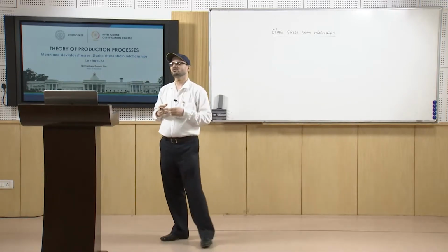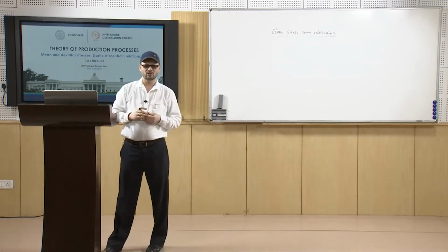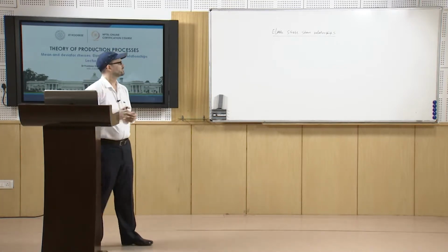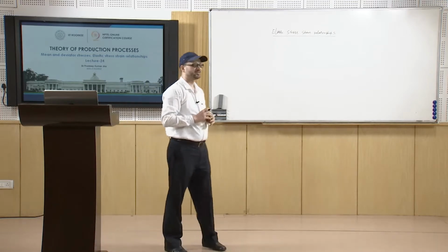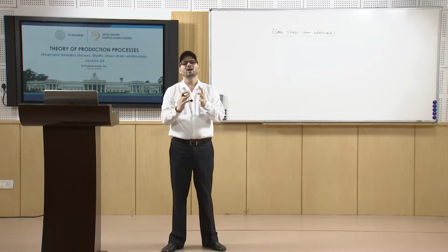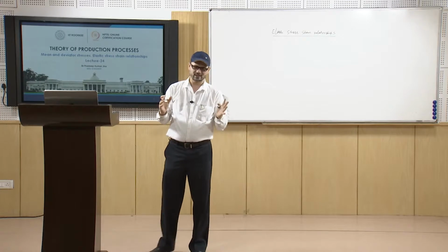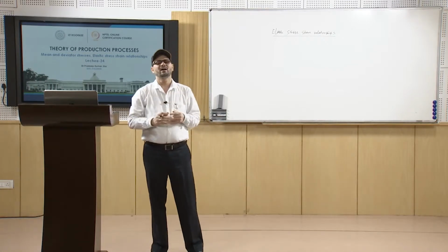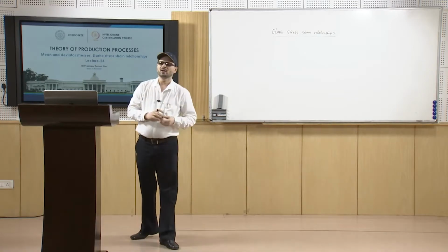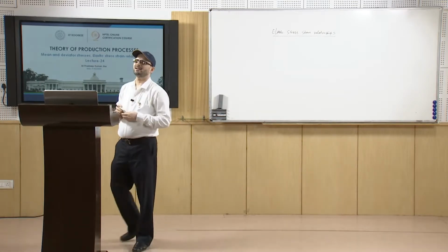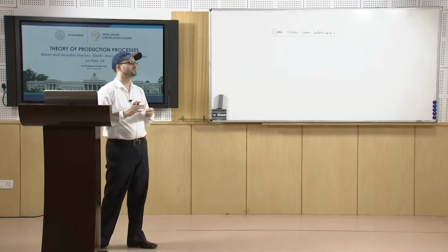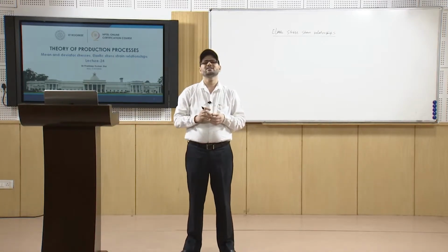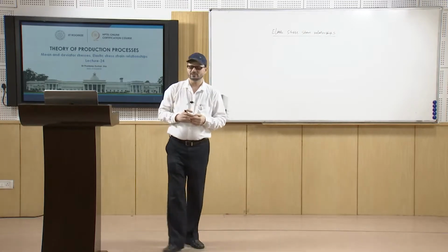What are these constants which we come across when we deal with the stress tensor and the strain tensor? Once we have to find the relationship between them, you have to put in the material properties, and then you get certain relationships between them, and these are known as constitutive relationships.